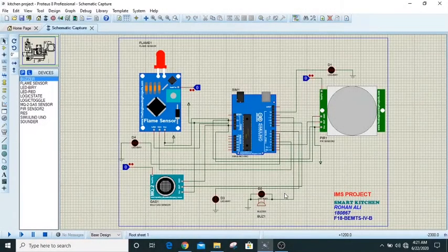I'm going to explain my semester project, which is a smart and safe kitchen. I used 3 sensors. These are also smart sensors based on Arduino. The first one is the IR flame sensor, which detects flame through infrared radiation. The gas sensor MQ2 is used for smoke detection or gas leakage, and the PIR proximity sensor for motion detection in the environment.